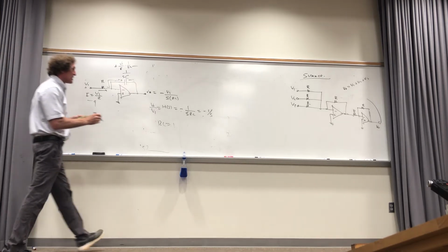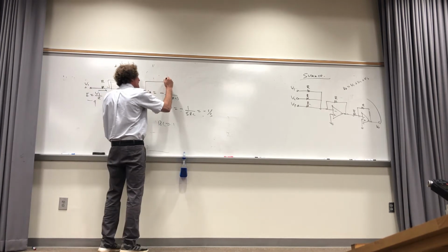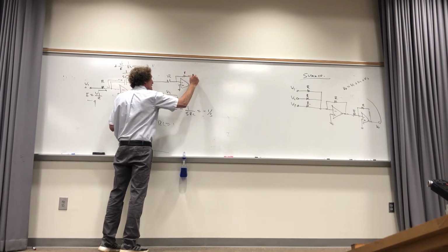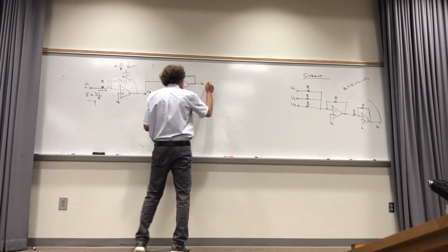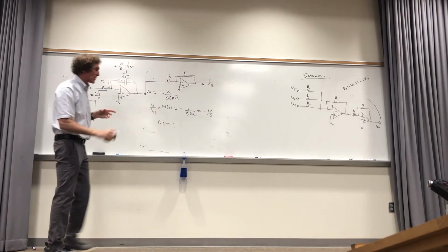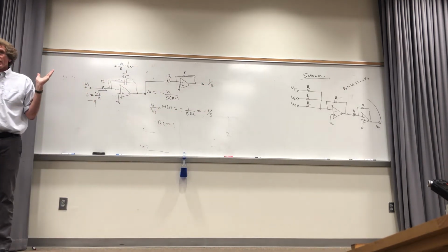With that, I can just take this into a circuit with R, that's an inverter, and now I have 1 over S as my transfer function for this circuit, input to output, from here to there. Do you all agree with me?